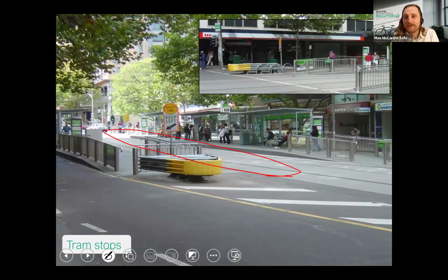They will absolutely put the blinkers on and neglect any of the surrounding road environment and just head straight across. So if you were doing a safe system assessment and there were bus stops or anything like that, be reasonable to assume that you'd have some relatively high risk pedestrian crossing activities, because people just want to make sure they get onto that bus.